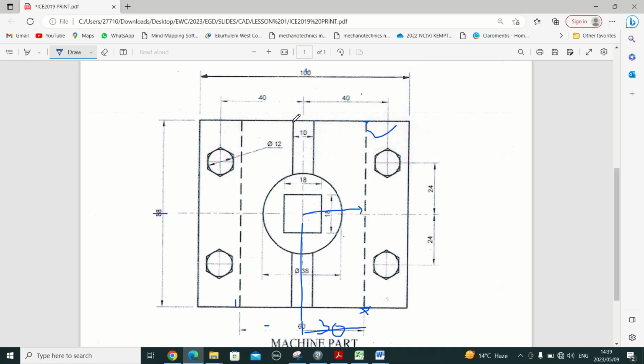Now we need to draw these lines here. So always analyze your drawing, guys, before you draw, and always use coordinates. Let's start with this side. How far is it from the center? It's half of this 10. That will be our x, going that direction. Our y, again, we're going to use 44, because from the center to here, it's 44. So x is 5, y is 44.